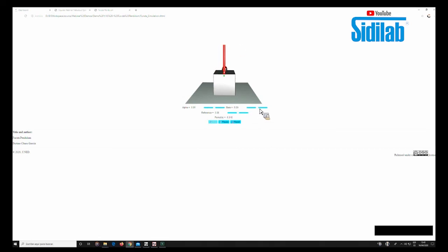And also I can change the beta, which is the angle to which the motor is looking at. Also, I have the beta reference indicated here just with the label reference, which allows me to move the position to which the motor is looking at. So if I move this to the right, you can see that green arrow moving in the representation, and the pendulum follows that angle. So that's called the beta reference because it is a reference for the beta angle.